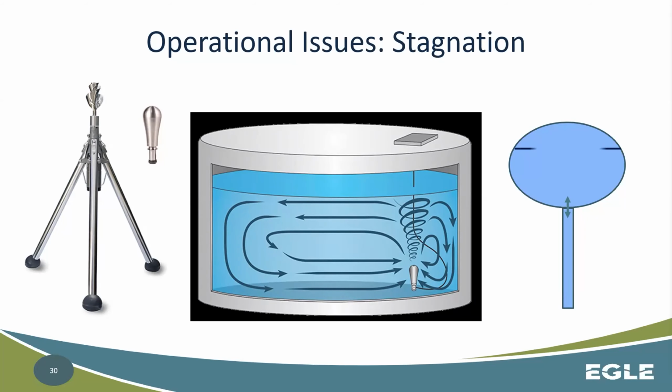Okay. There we go. You can also fluctuate by doing this. You can also fluctuate the heights of the elevated storage tank. That's what that animation was just showing, to get maybe some better mixing, better usage of water, so you're not having stagnant water sitting there for a long period of time, degrading and forming DBPs, things like that.